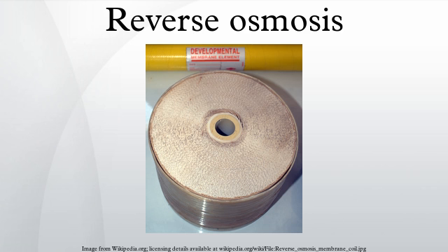Contaminants such as nitrogen compounds and phosphates can lead to excessive and unwanted algae growth. An effective combination of both reverse osmosis and deionization is the most popular among reef aquarium keepers, and is preferred above other water purification processes due to the low cost of ownership and minimal operating costs. Where chlorine and chloramines are found in the water, carbon filtration is needed before the membrane, as the common residential membrane used by reef keepers does not cope with these compounds.